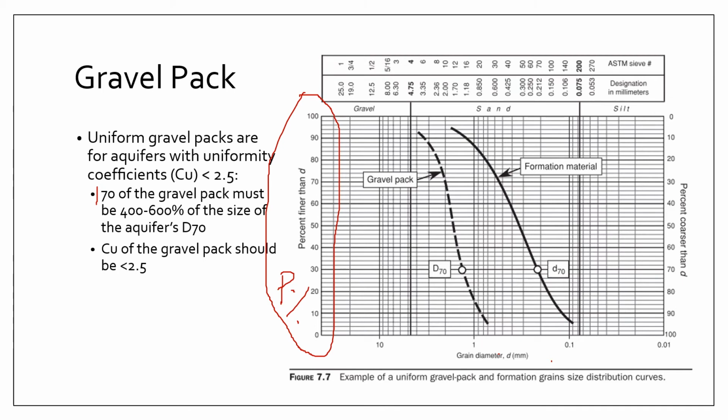When you have a very big grain size, let's try to extend this size plot chart for easier visualization. Let's say, for example, at 10 millimeters grain size diameter, you will have 100% passing, meaning at 10 millimeters of aperture, all the soil samples will easily pass through that size.